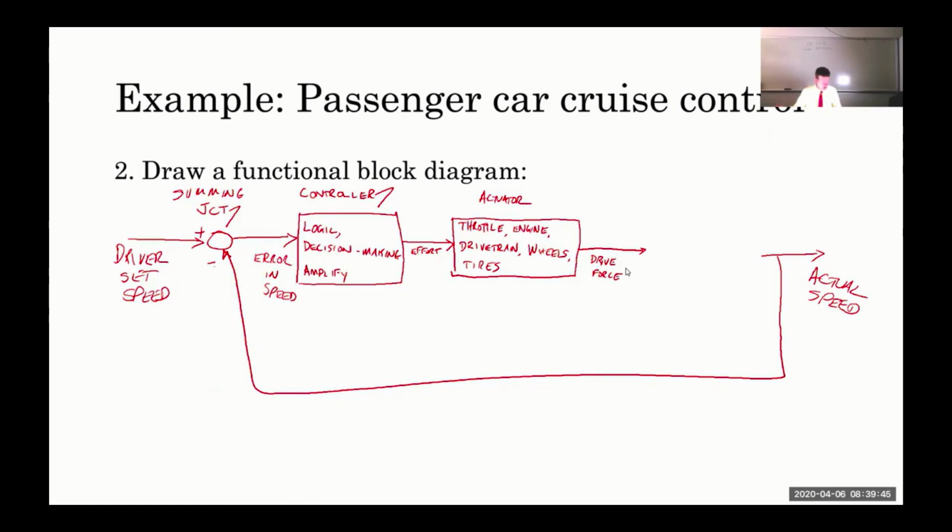So are we done? I mean, I've left a big blank spot in the diagram. We're not done. How is a better question. How do I get from here to there? Think about that for a second. Coming out of the actuator is a force. And if you like, units are your friend. We're not going to talk a whole lot about units in this class, but in terms of block diagrams, units are your friends.